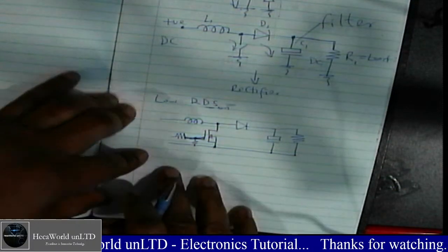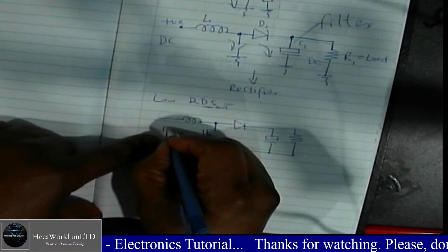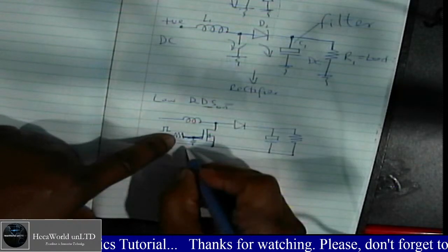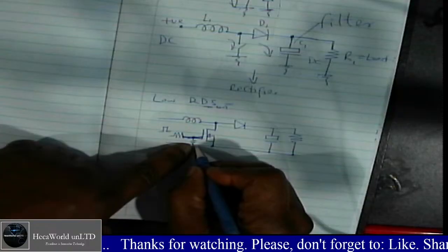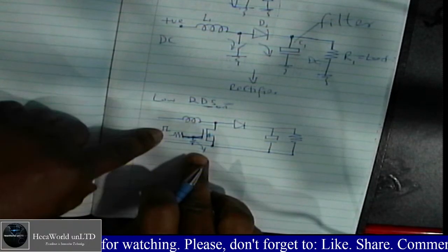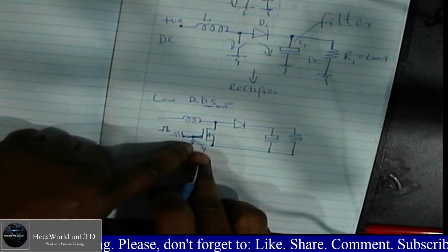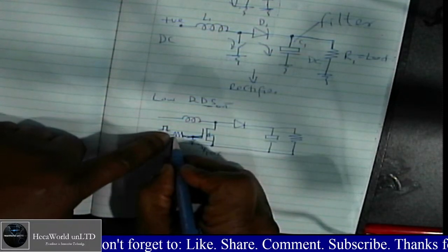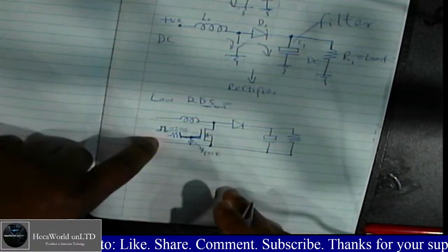Now I'll draw this bigger. I'm going to use pulse width modulation here, the gate resistor, and then there's a gate to ground resistor. This one here pulls it down so that when there's no pulse here, the gate is grounded. So I'm going to need that resistor. It can be 10K, you can use 10 kilo ohms and above. And for this one here, I can use maybe 220 ohms, something like that.